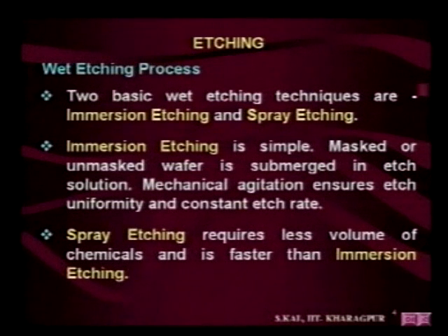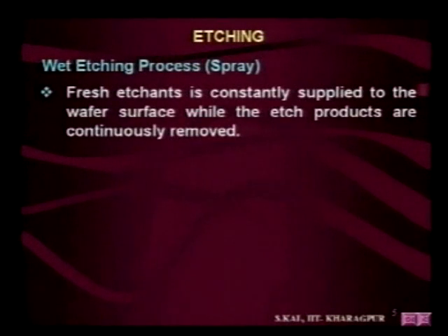Another good advantage of spray etching is that fresh etchant is constantly supplied to the wafer surface while the etched products are continuously removed. This is a very important point. In immersion etching, when the wafers are immersed into the liquid, etched products will form during the reaction.